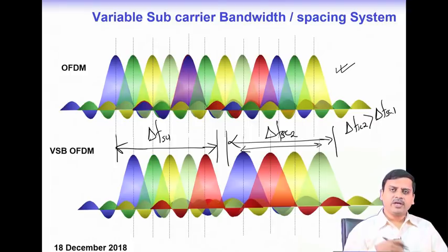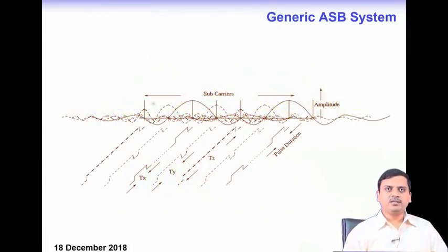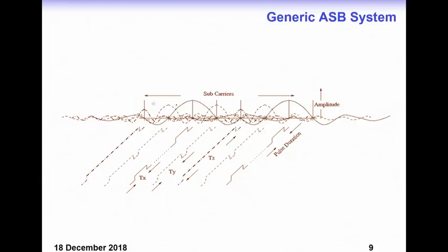Whereas, we can think of an extreme multiplexing of things where different bandwidths are multiplexed simultaneously, and correspondingly the different time domain pulses would also exist simultaneously. What we see is that the narrow band subcarriers have a longer pulse duration and the wider band subcarriers have a shorter pulse duration.